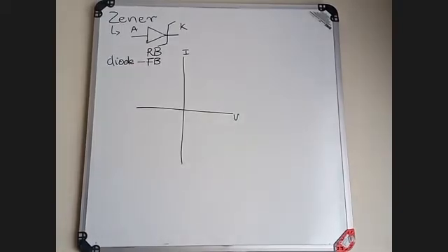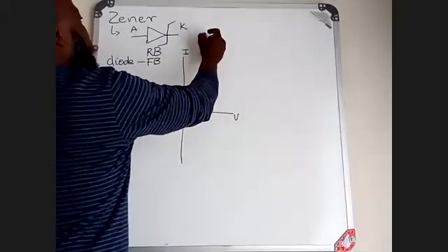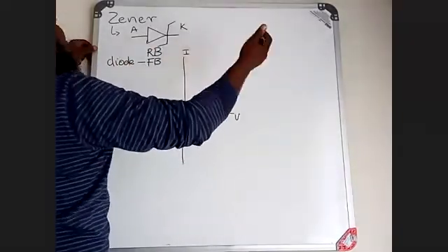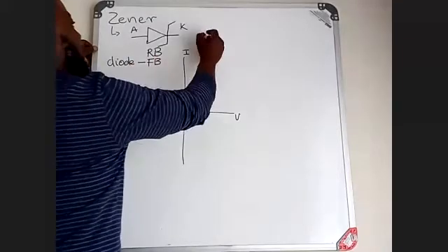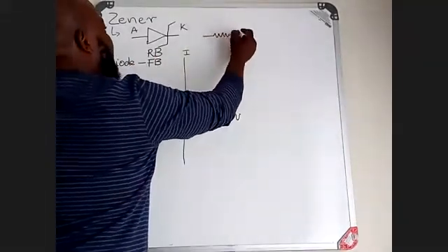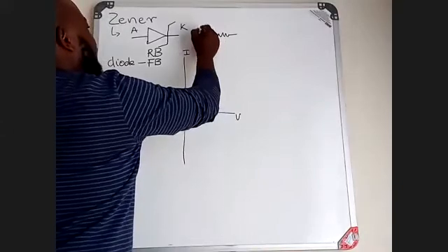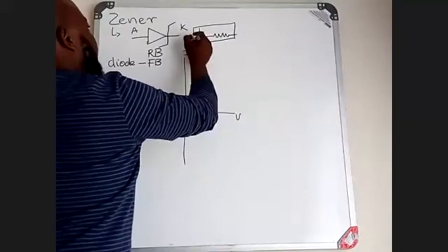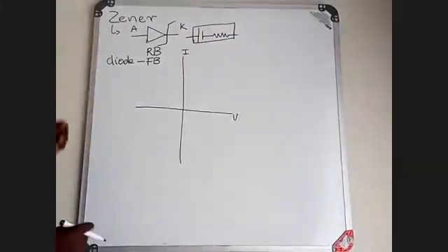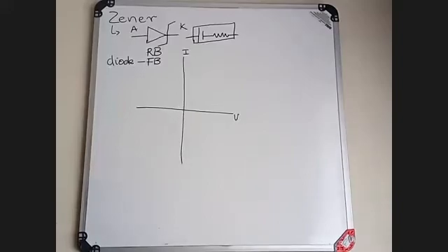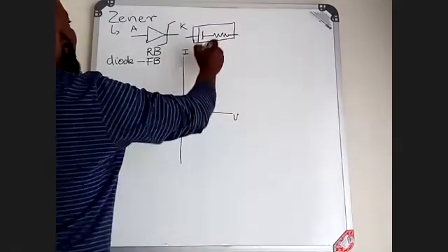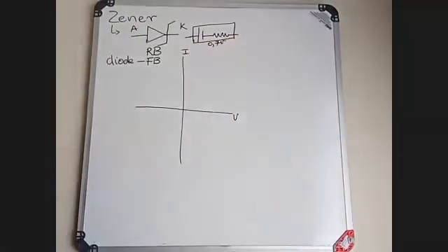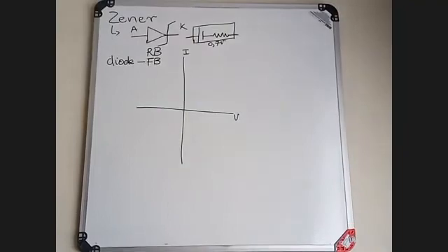With the normal diode, according to the practical model, as we've already discussed in chapter 2, you will have an internal resistance and a barrier potential, which means based on the material used, the voltage drop during forward bias is going to be 0.7 volts.